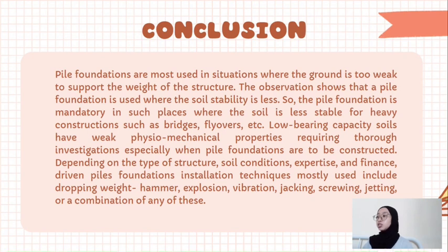Low bearing capacity soil has physiomechanical properties requiring investigation, especially when pile foundations are to be constructed. Depending on the type of structure, soil condition, expertise, and finance, driven piles, or what we know as displacement pile foundation, installation techniques most used include dropping weight, hammer, explosion, vibration, jacking, screw, jetting, or a combination of any of these.